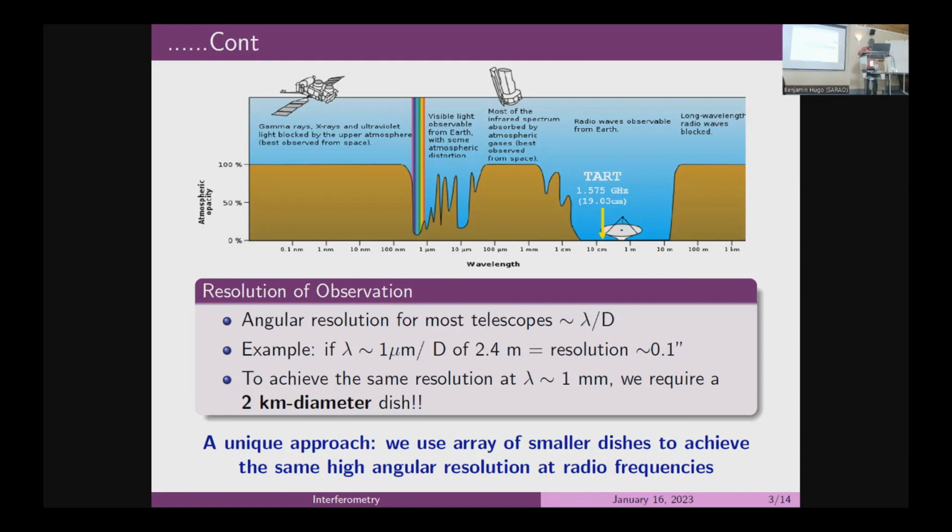You see, when we design and characterize antennas, the first thing you want to deal with is the size of the antenna, which is related to the frequency that you want to observe. And the resolution then becomes a factor of the inverse of frequency. In fact, if you are to design a MeerKAT antenna using this computational stuff, I have to scale it down. And when you scale it down, frequency goes up because it is an inverse. So what that means is that the longer the wavelengths you go, the larger the single dish antenna you need.